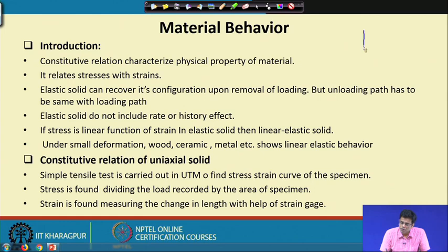That means, if loading and unloading paths are different, then the material may not be elastic. In this kind of material, where it loads here and the unloading path is here, this is not an elastic material. This is strain and this is stress. This kind of material we are not talking about.